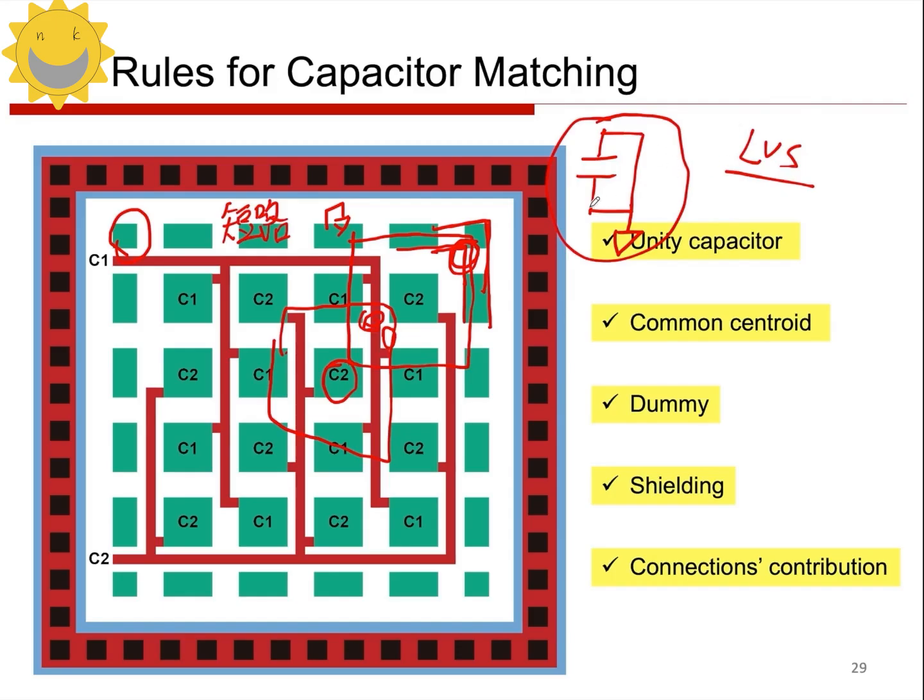What happens after ignoring the short-circuit device? It will not check these dummy devices. In this case, it can still pass. Or you can add such a device to the schematic diagram. I personally recommend adding such a device to the schematic diagram, because after all, if you ignore the short-circuit device, and you do short-circuit a useful device, it means that it is not short-circuited originally, but you accidentally drew it as short-circuited when drawing the layout.